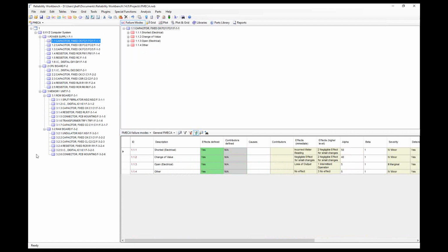By the way, this is an example of what's called a hardware FMECA. There's two styles: hardware and functional FMECAs. Hardware FMECAs would go down to individual components like this, listing the failure modes of those components. A functional FMEA or FMECA generally just looks at the systems or subsystems and what they're supposed to do, and it considers the loss of the function of that subsystem.